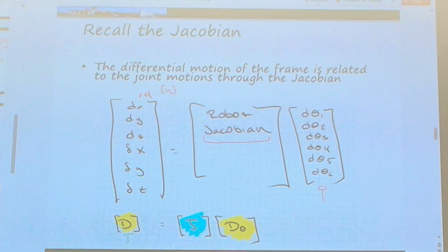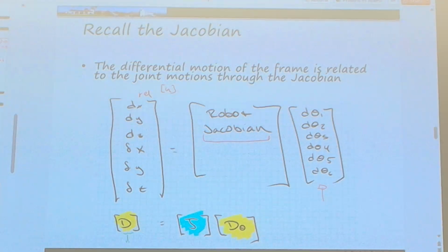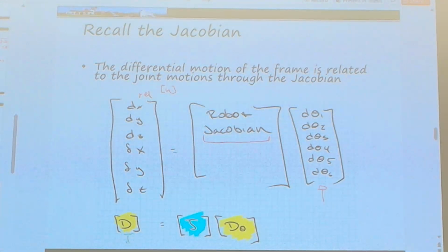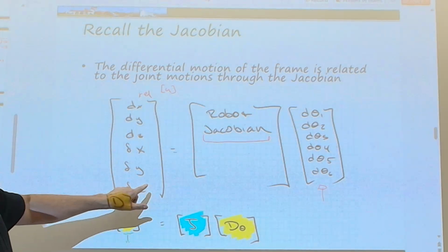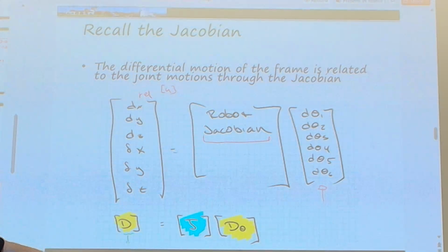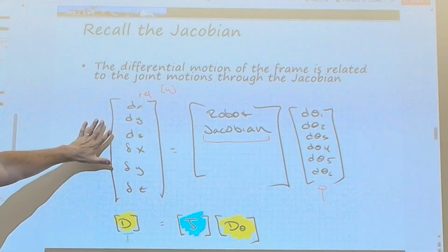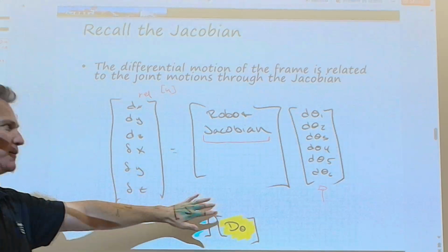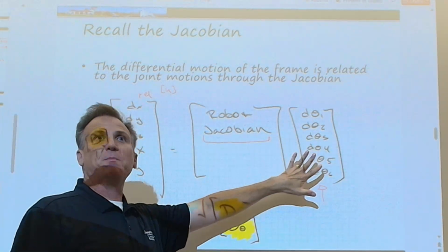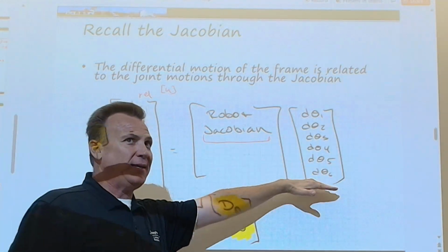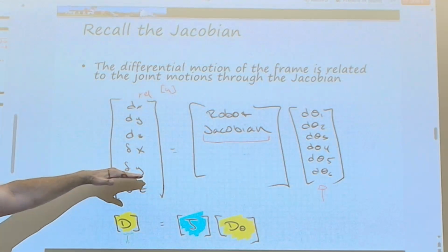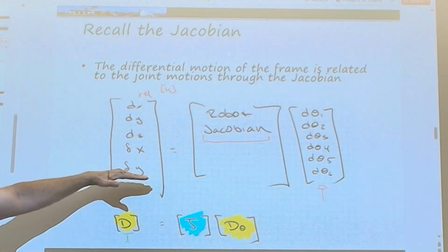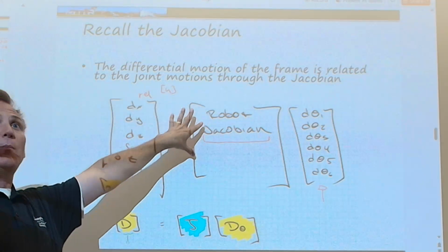So those thetas, when you change them, you're not going to get to a certain point exactly. What I understand is that when you adjust those, you don't get the exact point you want, because as these are changing, this is a velocity. It's a velocity vector, and that's a velocity vector, but they're two different spaces. If I try to integrate this, it does not mean I'm going to integrate that at the same rate, because I've got the Jacobian in the way.